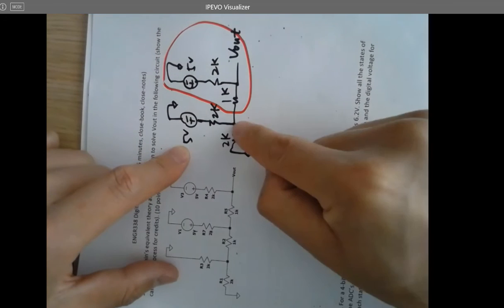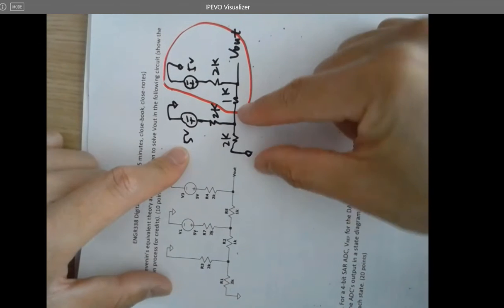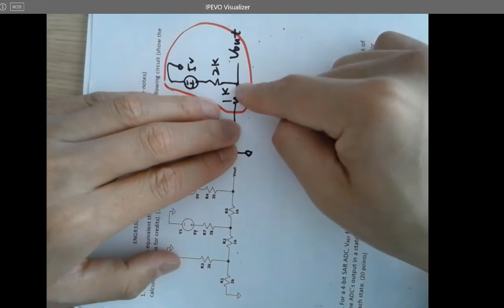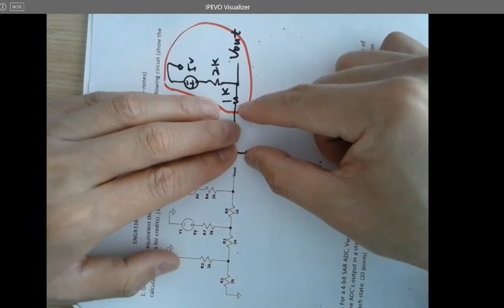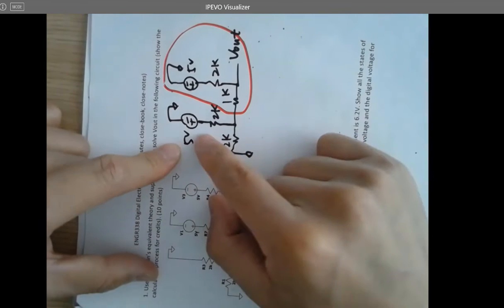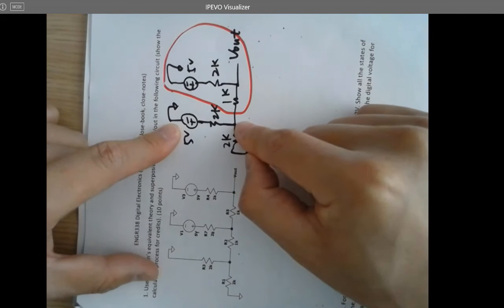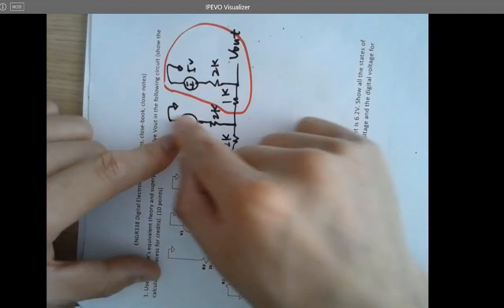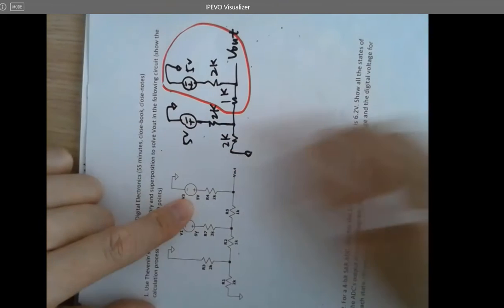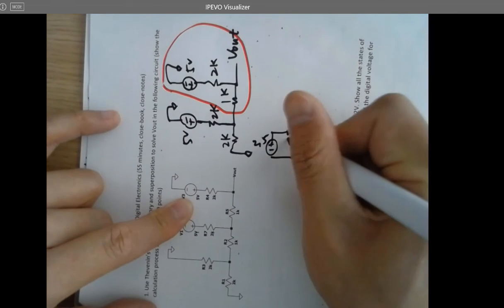So you're wondering why the voltage here? Because I'm treating this one as a load. So whatever from this point to the ground will be RL. I don't care about what's inside, it's just a black box. It's a load. I'm going to remove it when I'm doing ETH and RTH. So whatever the voltage here will be ETH, and apparently that's a voltage divider. That's dividing this by 2 halves. So I'm getting 2.5 volts over here, which will be the ETH. And if I short this guy, I'm looking inside. It's just 2 resistors in parallel. That's 1K. So the equivalent circuit of this one will be definitely 2.5 and 1K. Right? Done.